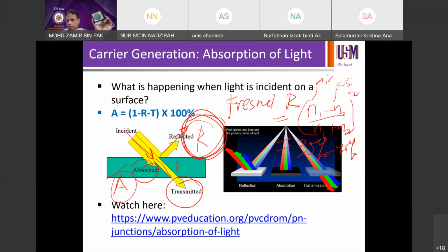On the other hand, on the blue silicon solar cells, you couldn't see any reflection. You can just see blue. So that means the reflection level has been reduced. On the original crystalline silicon wafer, monocrystalline, a single crystal, if you measure the reflection level, it's roughly about 35% to 40%.